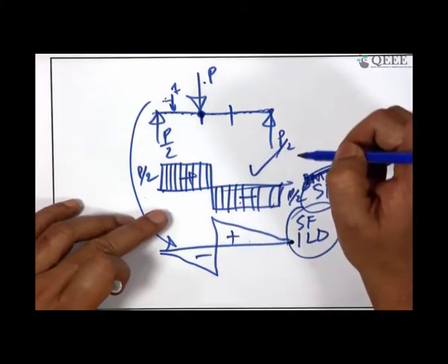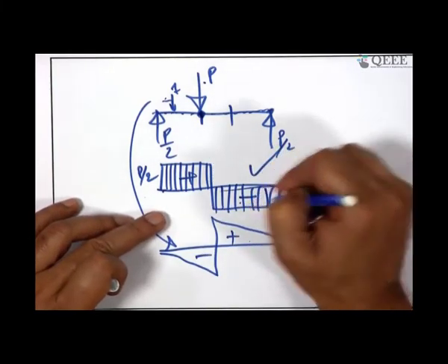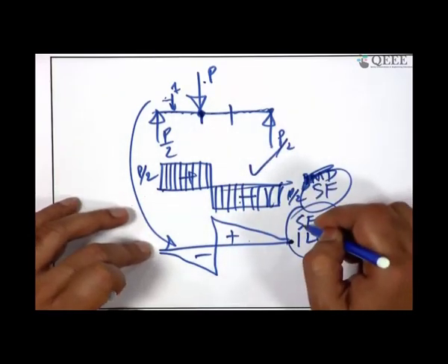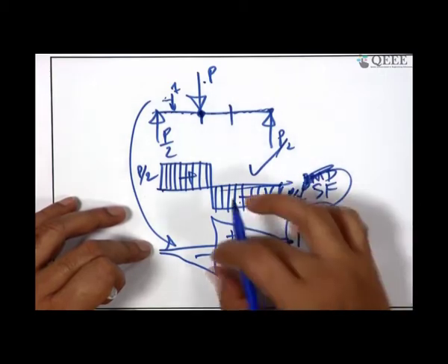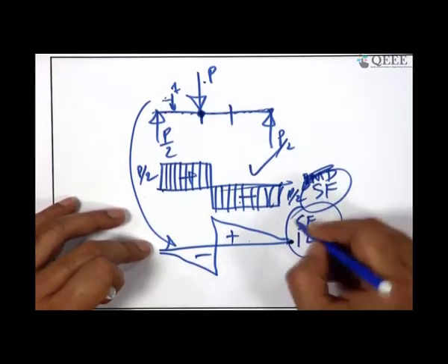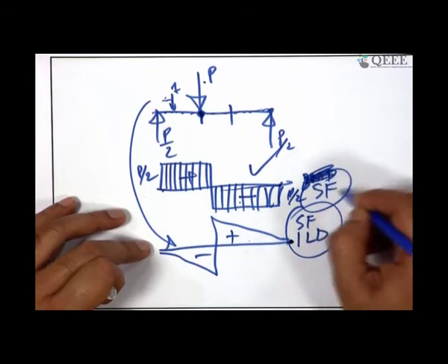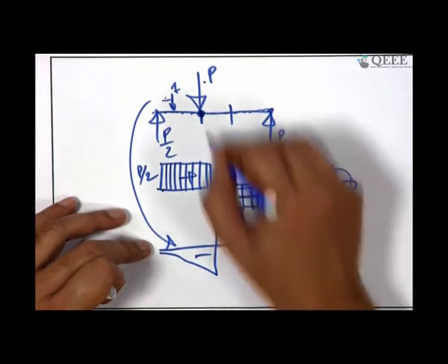If I said bending moment, I unconsciously drew the shear force diagram as well as the influence line diagram for the shear forces. I was concentrating on explanation, that is why it slipped from my mouth that it is the bending moment, but it is actually the shear force diagram itself, and this is the shear force influence line diagram for a particular point.